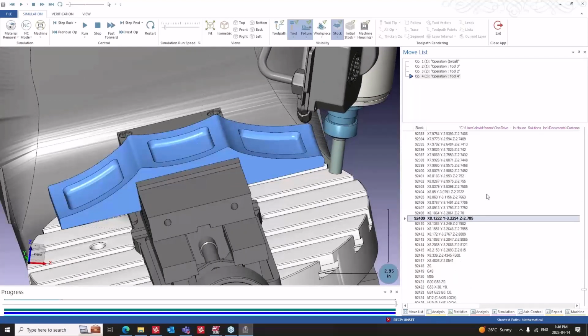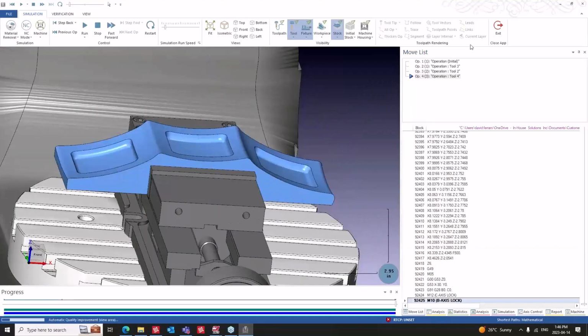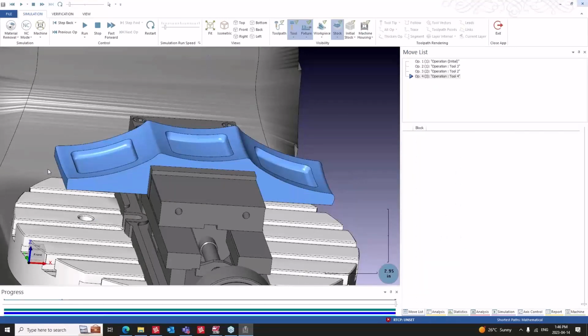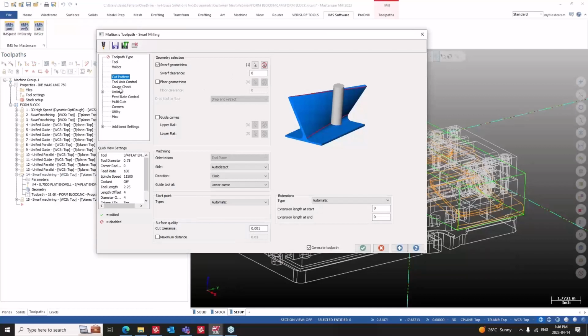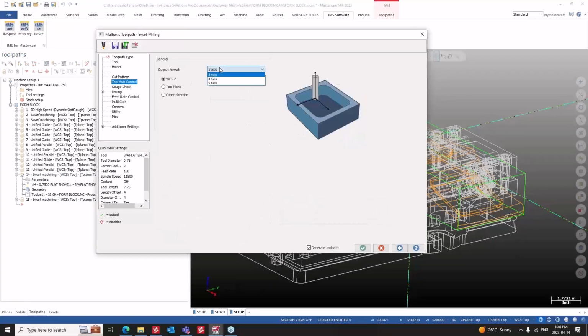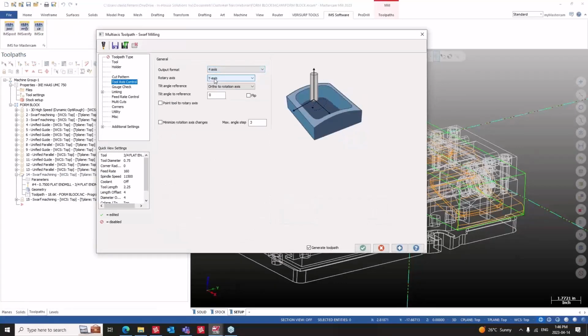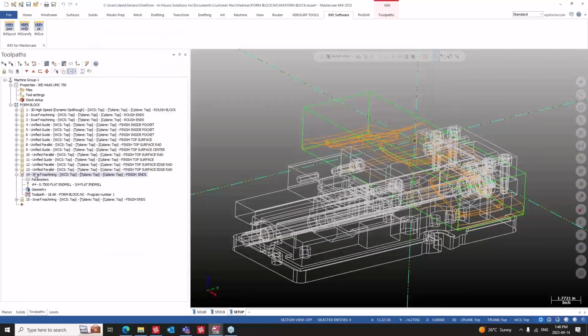So that side seems to be fine, no problem. It's only the one side that needs to be fixed. So if I back out of this, and if I've changed the program here because of the ends here, I know what the problem is. I set it, so you'd see the collision and everything, but there's an axis problem here, tool axis. It's set to 3 axis. So if we set this to 4, it would automatically. So let's just see if I do this.